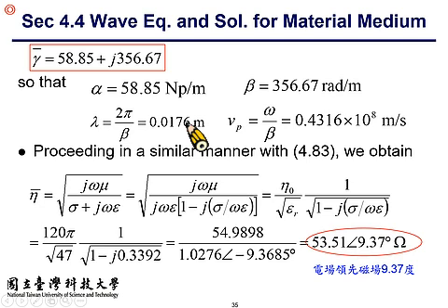And next, let's check the intrinsic impedance eta. Because this frozen meat has a non-zero conductivity, non-zero loss tangent, the intrinsic impedance eta is not a real number, it's a complex number. Put in those numbers, you end up with a complex number as 53 with 9 degrees. So in this frozen meat, the electrical field intensity is still much greater than the magnetic field intensity, by 50 times. However, the electrical and magnetic field intensities have a phase difference of nearly 10 degrees as a consequence.